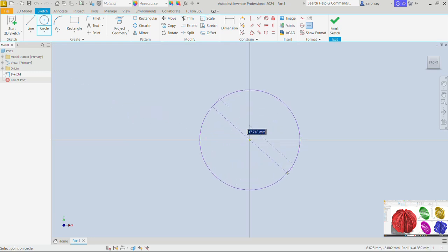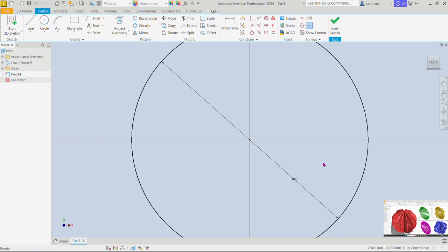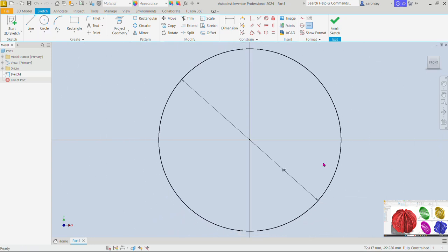We will dimension using the dynamic input box. The diameter of this is 180. Just type that in there. You can press enter. Now our work is off focus. You can press escape to get off the circle command first, and then you double click your scroll mouse button so you have your work in focus.